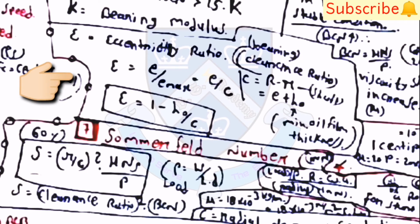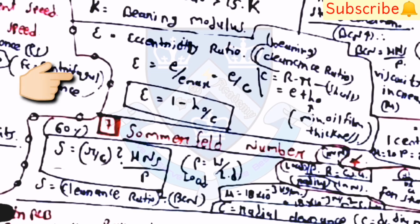Epsilon is equal to E by E max, which is equal to E by C, and epsilon is equal to 1 minus H naught by C. Then C is equal to R minus r, which is equal to E plus H naught, where H naught is equal to minimum oil film thickness, capital R is equal to radius of the bearing, and small r is equal to radius of the shaft.